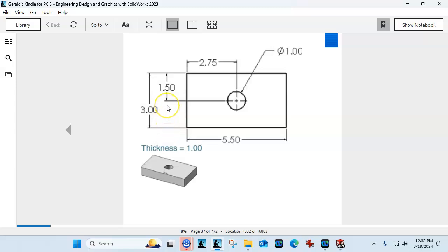If there is a part in inch, the ANSI standard won't have a leading zero. Metric or ISO will have a leading zero. So that's one clue. Also, the metric doesn't often have fractional or decimal 0.75s. They do show up, but maybe not as common.